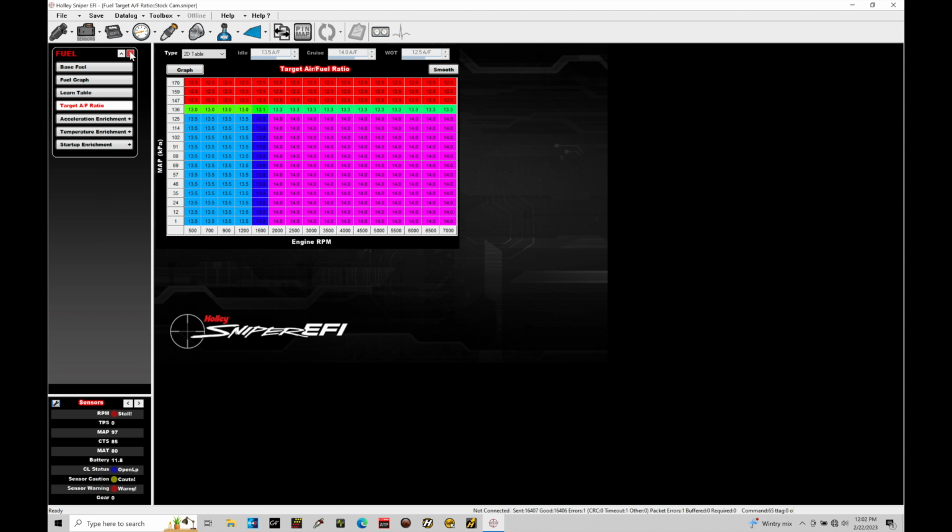And it does make sense in working with these in terms of having to remember Alt and then the letter is going to usually designate to stand for something such as the table is represented as. So for example here, Alt N would be for nitrous, or Alt S for spark timing, or in this case, Alt A for acceleration enrichment. So those make sense. So for other keystrokes like Alt-X or Alt-Z, they're a little bit more difficult to remember, but they're present, and that's why we're covering them here in this tutorial.